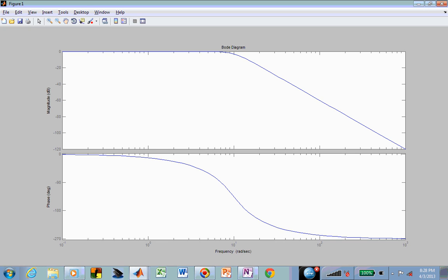We will be down at 3 dB. Our phase, because it's third order, is going to be 3 times minus 45 degrees. Eventually, for high frequencies, because of the third order behavior, our phase is all the way at minus 270, and we're rolling off into the stop band at a slope in the magnitude response of minus 20 times 3, or 60 dB per decade.